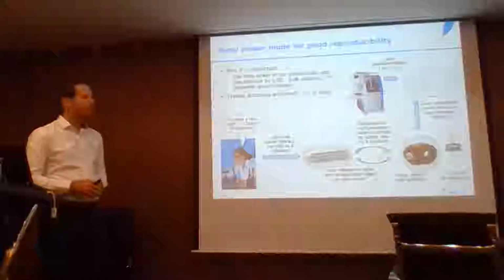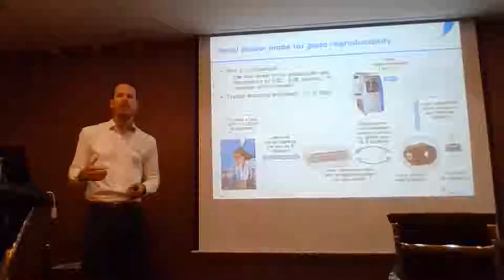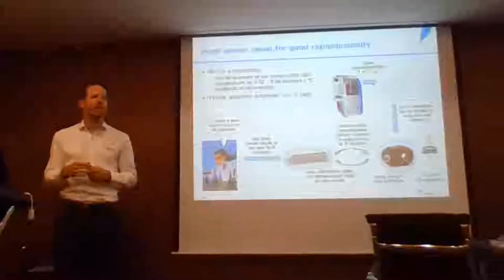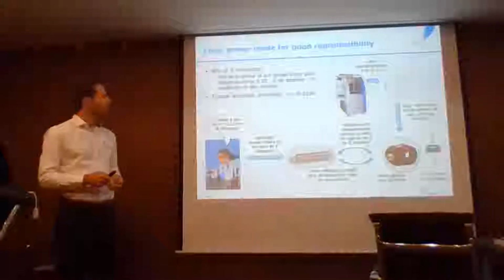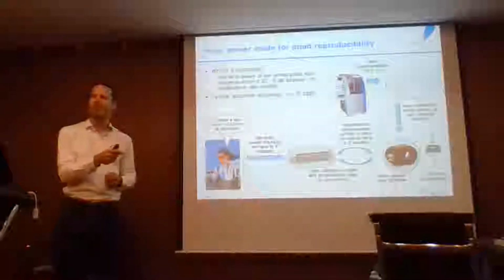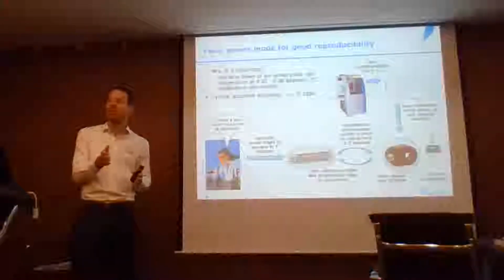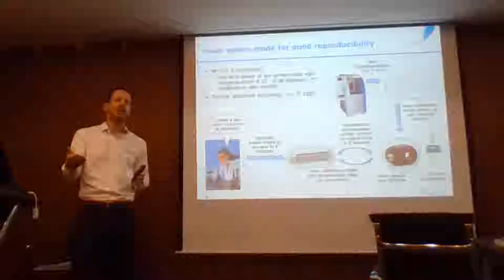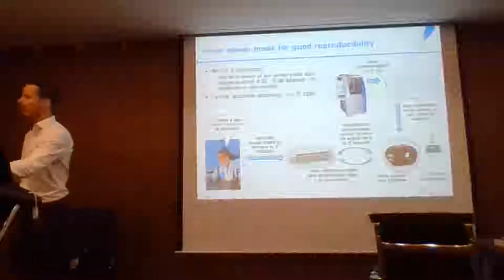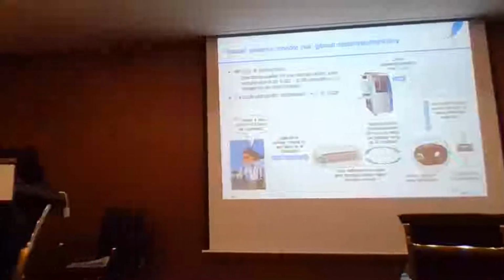So one important part of driving our lens is the focal power mode. We call it focal power mode. It's a bit of an Optotune word creation. Basically, it means that we control the optical power of the lens in diopters, and the driver will calculate what is the best current to output to the lens to get the necessary optical power. So I'll draw a bit how this is done very roughly on the whiteboard.